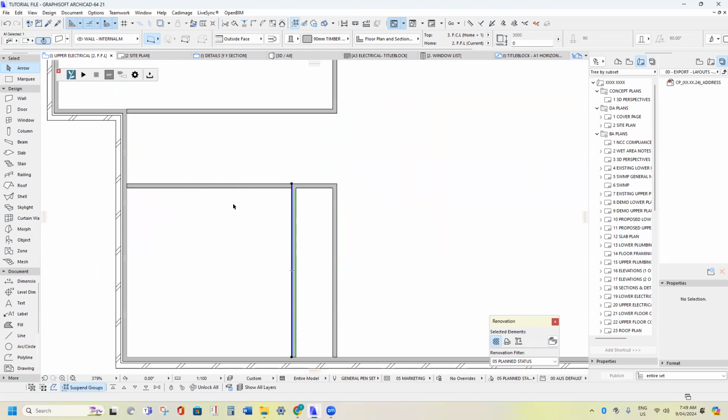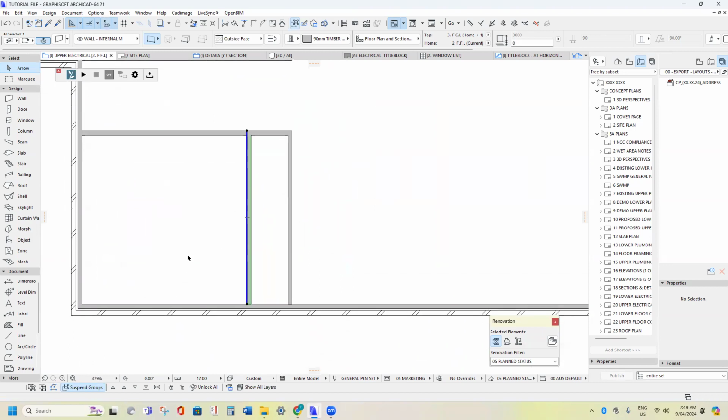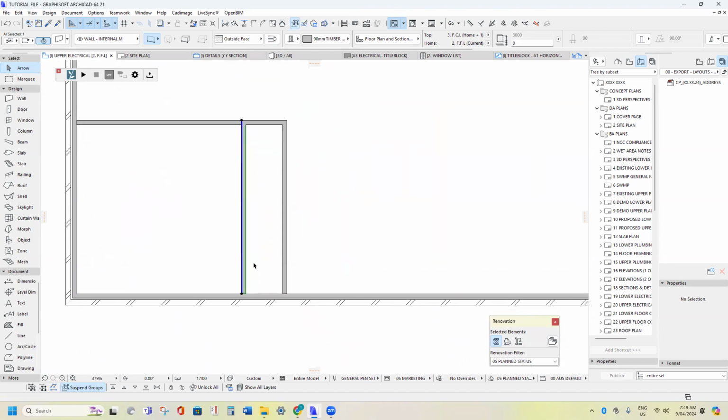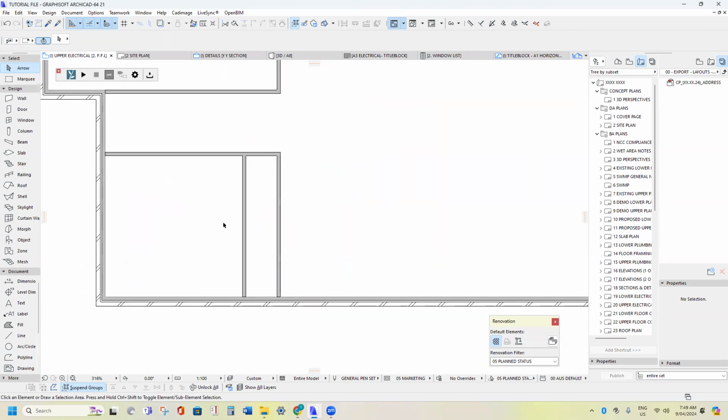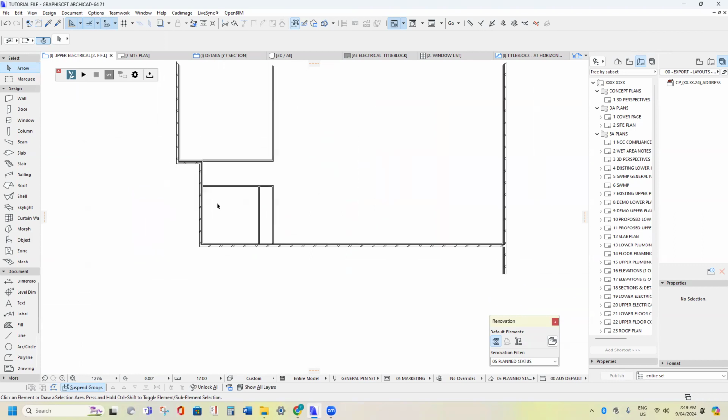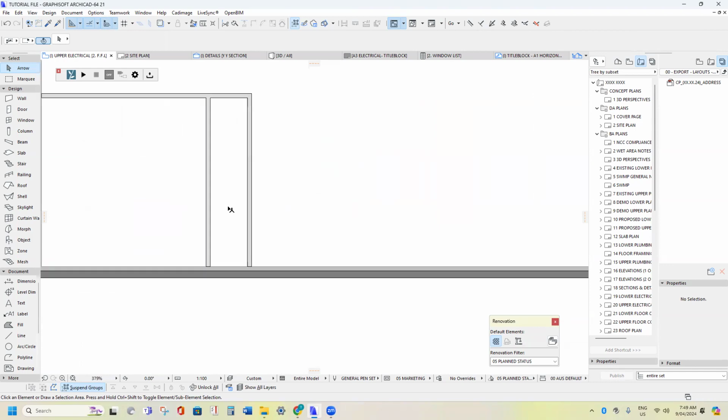So that's the master bedroom, 3600 by 3600, or 3.6 meters by 3.6 meters. That's a good sized master bedroom. It's generally the minimum I make a bedroom that allows a king size bed to fit in there and still have a decent amount of space to move around.